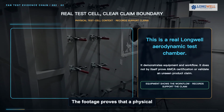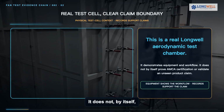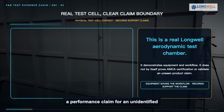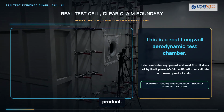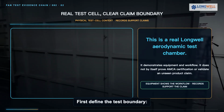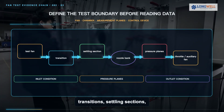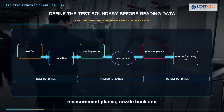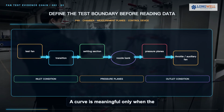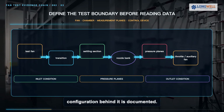The footage proves that a physical fan, chamber, and measurement system exist. It does not, by itself, prove AMCA certification or validate a performance claim for an unidentified product. Keep that boundary clear. First, define the test boundary: the test fan and its appurtenances, inlet and outlet conditions, transitions, settling sections, measurement planes, nozzle bank, and the device used to control the operating point. A curve is meaningful only when the configuration behind it is documented.